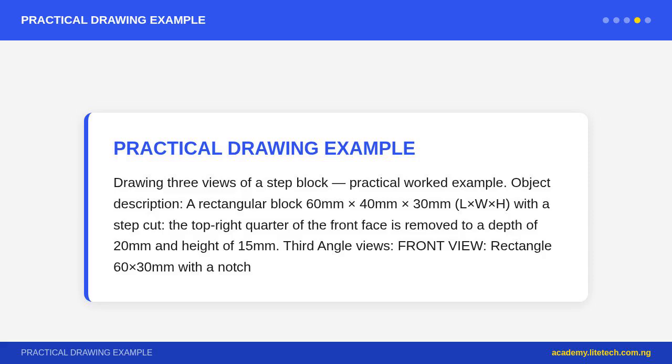Answer. In first angle projection, the view is placed on the far side from the observer, the projection plane is behind the object. The plan view appears below the front view, and the left side view appears to the right. In third angle projection, the view is placed on the same side as the observer, the projection plane is between observer and object. The plan view appears above the front view, and the left side view appears to the left.